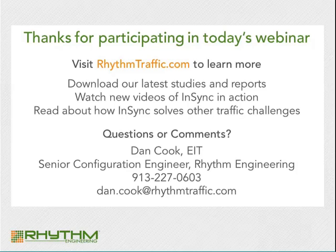Dan, can you talk about InSync fog mode? Yeah, so when you're running video detection, as well as InSync Fusion, there's a fog mode that will kick in if the visibility on that camera decreases. And what it's looking for is areas of contrast. When the detection zones are initially set up, the user will set up fog zones. We recommend setting up 2 or more fog zones, and you draw those around areas of high contrast,